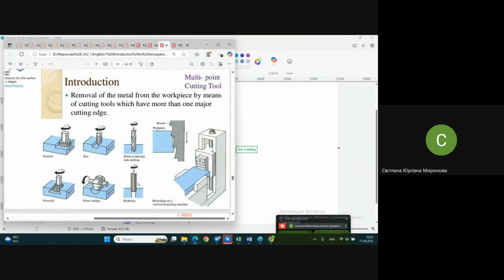But imagine what I said about abrasive cutting. What if you have thousands of tiny blades? Certainly it will be much better. Yes, of course, but we also need to remember that the thinner the layer of material we can cut, the longer the cutting process. Imagine you cut something with a thick piece, or you cut it with the thinnest layers one by one, how long it takes.